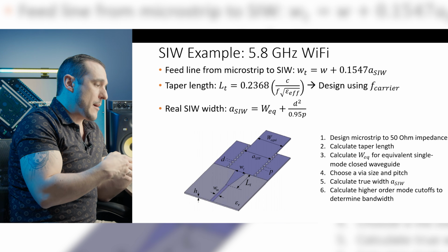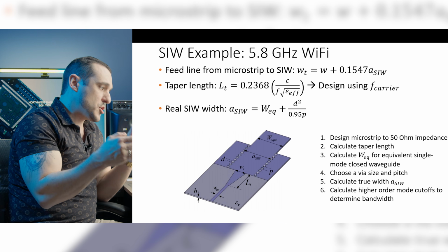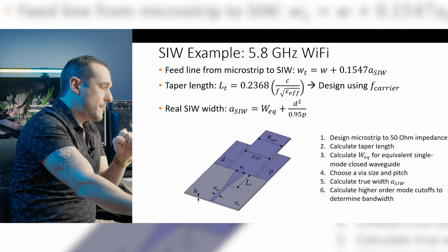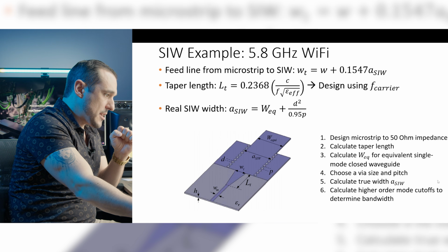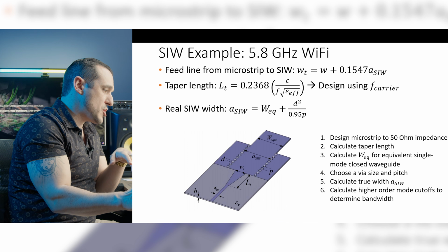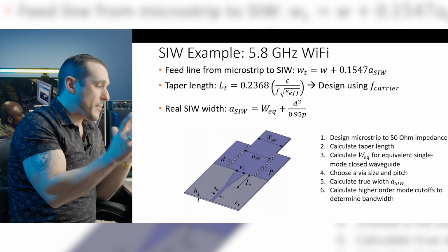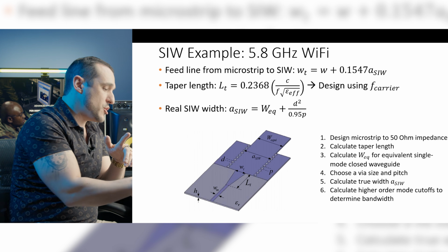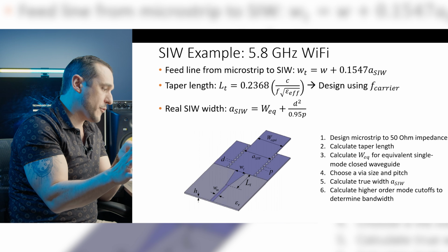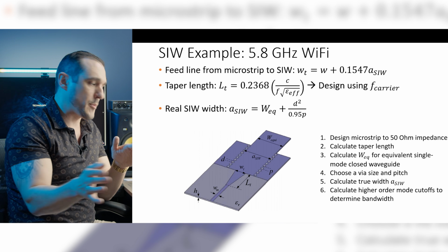So here's the basic geometric model for a substrate integrated waveguide that you can then use to calculate all of the geometric parameters that give you optimal signal transmission into this waveguide. So here you can see the calculation process here on the right. I'm not going to go through each step. Instead, what I'll do is just jump into the calculator and then show you how you can use that to calculate all of the different cutoff frequencies for the various electromagnetic modes.